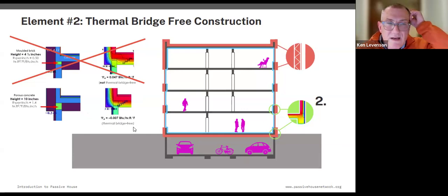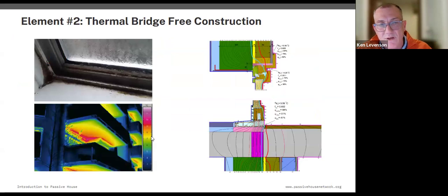So these are the sorts of things that we look at when we do this, because what we want to avoid, in tougher climates and cold climates where you have poor thermal performance, is condensation. We don't want mold. We don't want the building acting as a radiator to the environment. We want to keep the conditioned air, the conditioning, in the space itself.